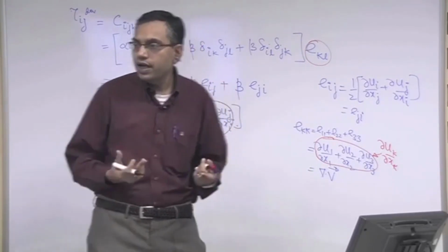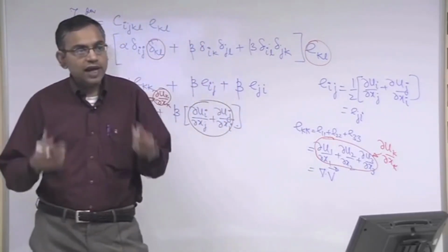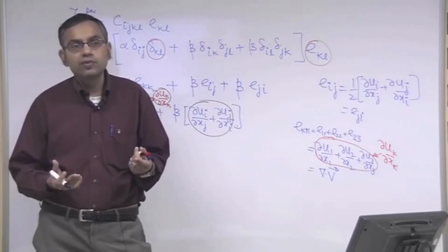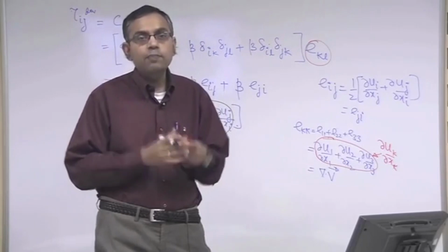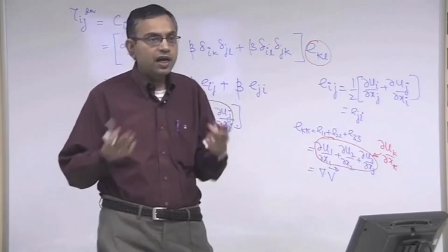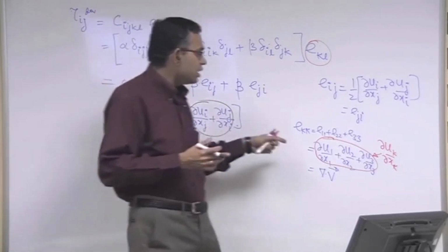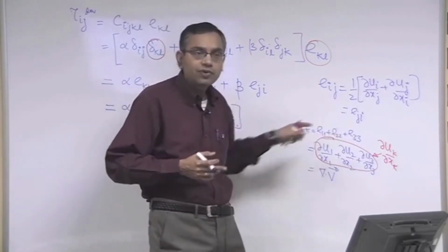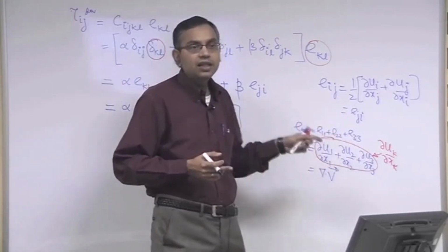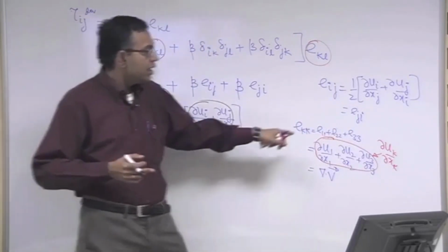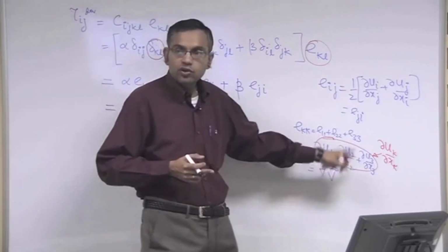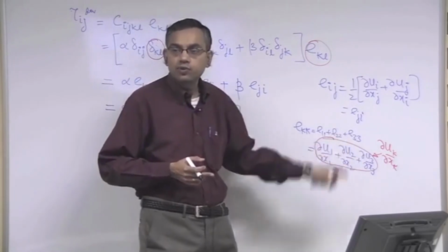On the other hand, incompressible flow is a pure kinematic concept, following from the consideration that if a fluid is not suffering from any volumetric strain, then the flow can be considered incompressible. So, incompressible flow should not be confused with incompressible fluid.